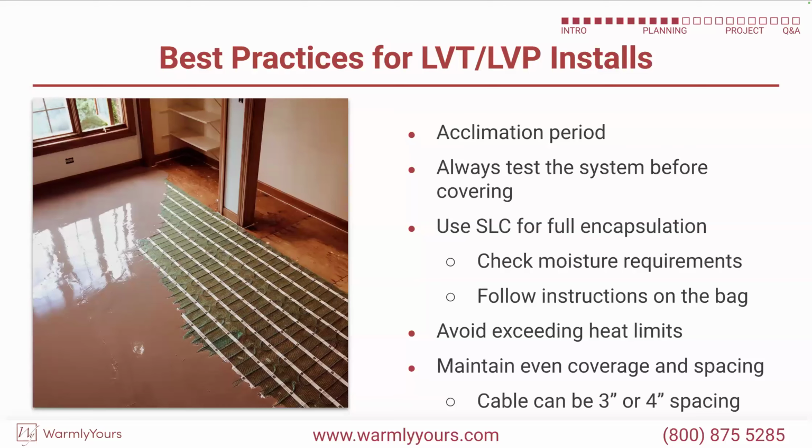First of all, never try to mix thin set thinner because it's cheaper. Never try to do that because you have to mix the thin set as it's shown on the instructions, and you have to mix the self-leveling as it shows on the instructions. You're never going to go, on this job, I think I'll make it a little bit thinner, or on this job, I'll make it a little bit thicker. There's no decision to be made. You're mixing it in the proportion that the bag tells you to. So there's no custom mixing when it comes to these products if you want to get good results.